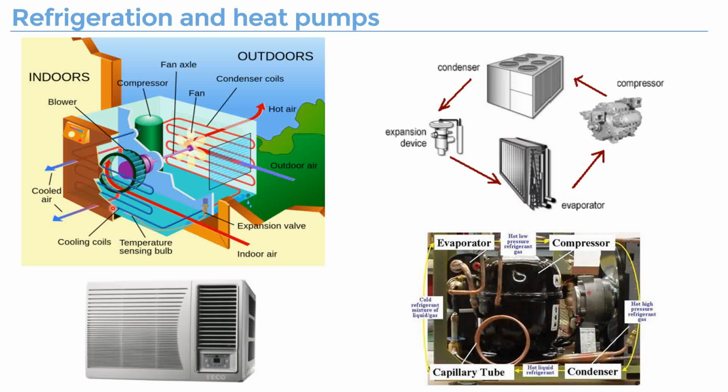Yes, so when we say evaporating, something has to absorb the heat. So this material itself gets evaporated. So every time we say evaporator, also evaporating or condensing, we are talking about the refrigerant inside this circle. When the refrigerant gets into the evaporator, it absorbs the heat from like the indoor environment. So the refrigerant itself gets evaporated, changing from the state of liquid to gas. When it gets into gas, it goes to the compressor to be compressed. When the gas is compressed, it's high temperature and high pressure.